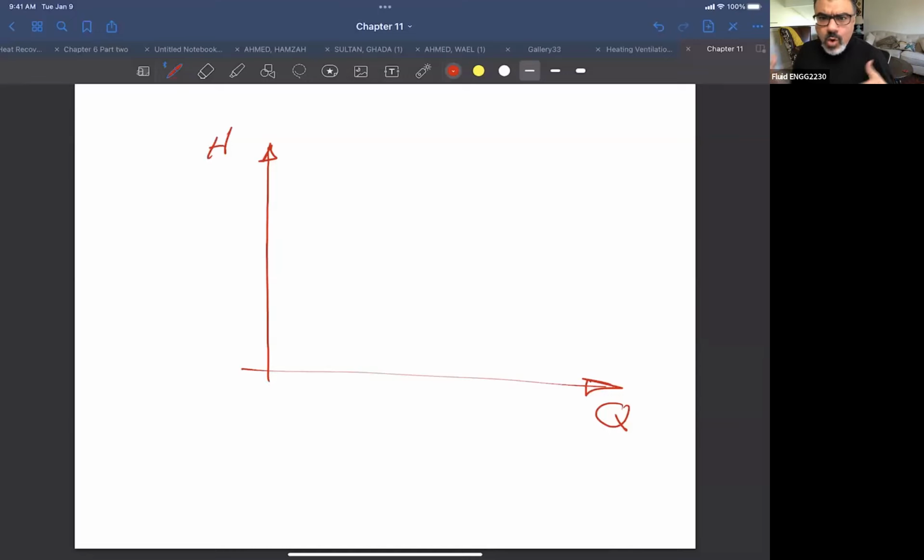And people were asking why head, because if you remember back when we started talking about the Bernoulli equation and the hydraulic gradient line and all this in fluid mechanics, when we are dealing with fluid flow, we manage to put all the energy in terms of heads. So it will be much easier to add those values together and present all the information in terms of head of fluid, right? So head here means the value of the pressure divided by rho g, or gamma of the fluid, in order to get the pressure head.